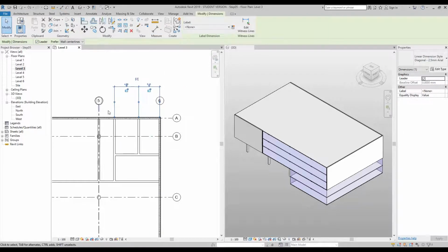As you will notice on your dimensions, you have two lock symbols and your dimension is currently blue, and just north of that you'll see a little EQ button with a red line between it. I'd like you to press the EQ button and you will automatically notice that our wall has shifted to the left and is now equal within that space.